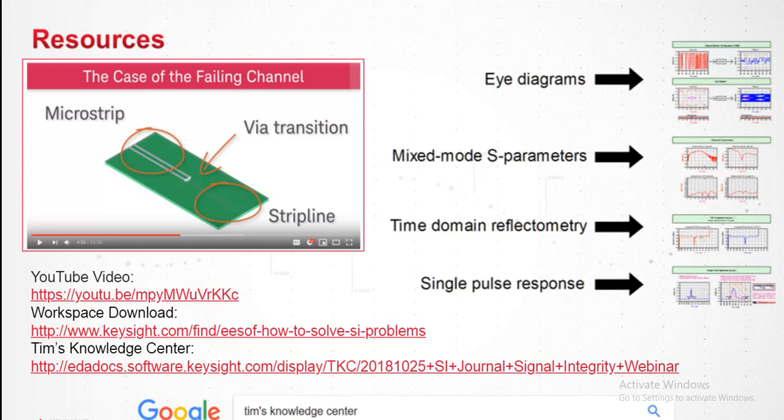Here's a question from Keith. How does the Nyquist frequency factor into signal integrity issues? It is very important, since when you have a data pattern, say PRBS, there's an underlying clock running at the Nyquist frequency. Once you have the Nyquist frequency, you'll be able to dissect this. You have the odd harmonics, and you want to use the Nyquist frequency almost as a reference. If you are doing really well at the Nyquist, and nothing else is going wrong at the odd harmonics, you'll be doing fine in the eye. That's usually the starting point.